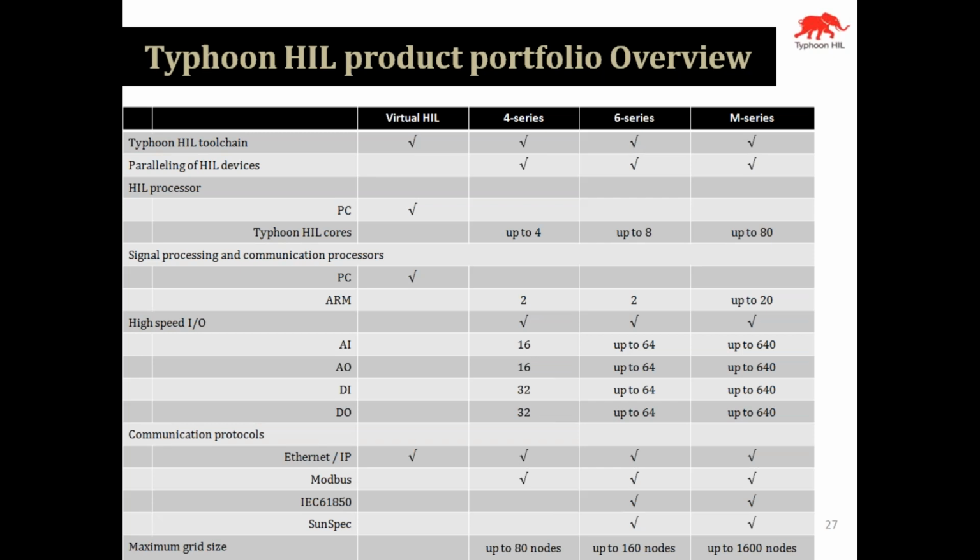All the parallelized HIL devices are synchronized with the master HIL, that is the one with ID 0. Here we start counting from 0. If I'm using 3 devices, then I count device ID 0, ID 1, ID 2, so these are the 3. If I'm using 2 devices, then I count device ID 0 and device ID 1. So don't be confused: if it shows device ID 0, it means you are connected to one device.